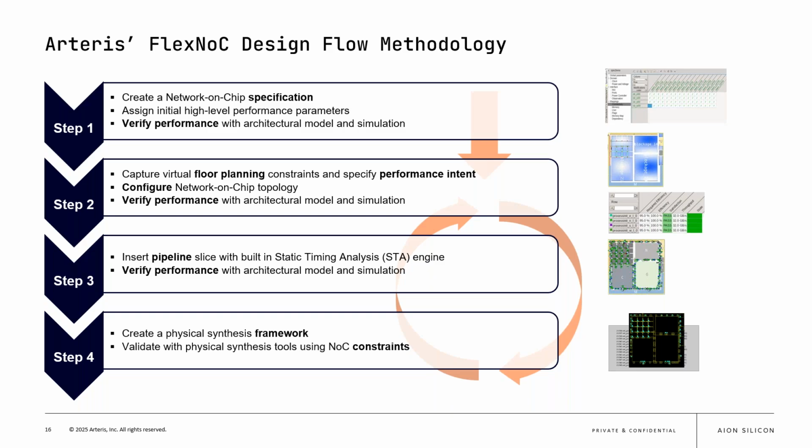So we see here that FlexNoC 5 brings a physically aware design flow that ties the NoC topology directly into the system on chip floor plan. Instead of building the interconnect and hoping it fits, we actually align sockets, paths, and pipelines with real physical distances.